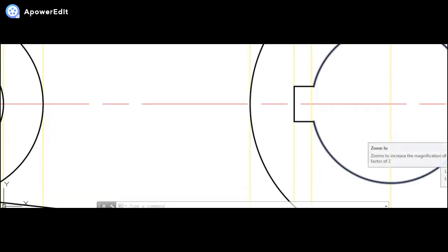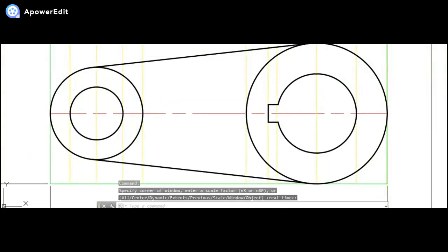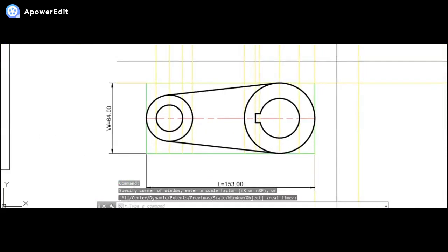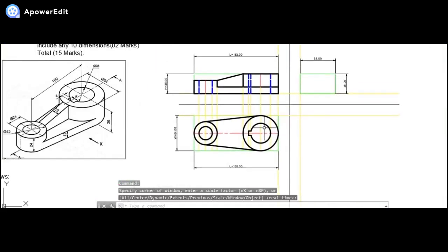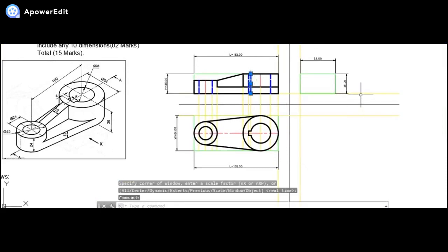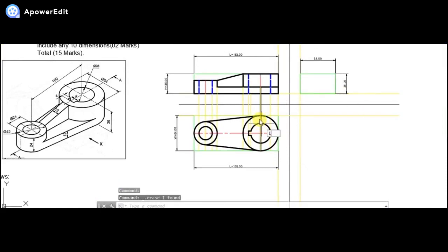Very specifically and very clearly, these edges are to be projected back in the front view so that we get the exact location of the hidden line over there. So let's draw the exact location of the hidden line over there in the front view. For that sake, this is the correct one. Only this one I am erasing as of now, and I will be projecting them back straight up.